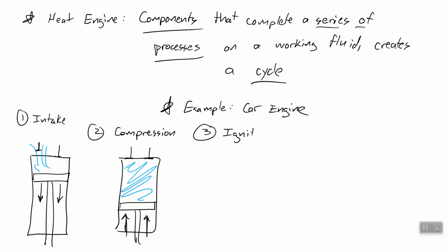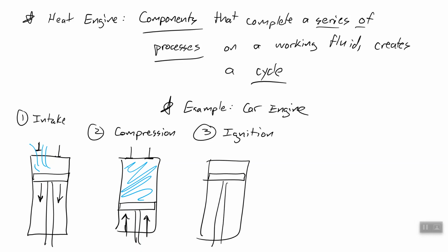Then we have the third step, ignition. So little did you know that some gasoline has been squirted into the air. And just when you've compressed it all the way to the top and the air is already so hot and so pressurized, you do a little spark and you ignite all of the gasoline.